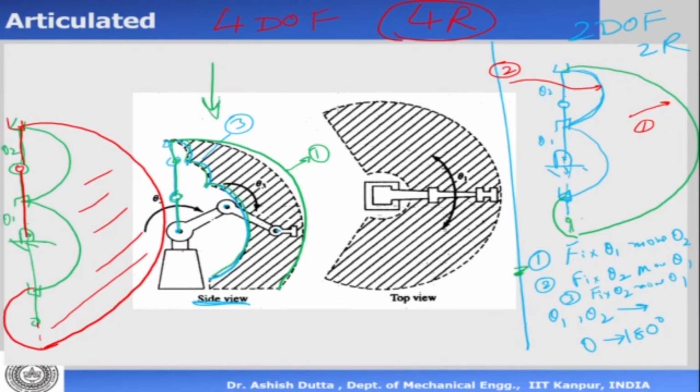When I see from the top, we are going to look at this profile. This is a planar area, right? So when we see from the top, it will appear as a straight line. So this is my straight line. Now the degree of freedom 1, the first one, is a revolute axis, so it can rotate the full axis from this side to that side. So the straight line can move like this, something similar to the previous one in the case of the cylindrical robot.